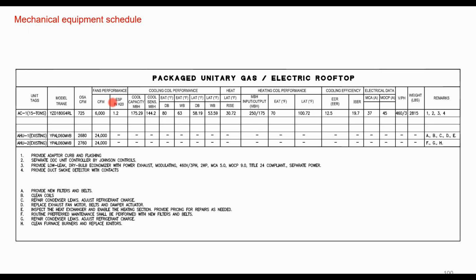There's a question there about exhaust fan energy being considered unregulated. Exhaust fan is not considered unregulated. If you look at Appendix G, the way that it accounts for fan energy, it's total system fan energy, right? So you have to account for supply, return, exhaust in your total calculation. So it is not considered process. If you had a kitchen that is doing exhaust, that is a process exhaust system, so that would be modeled neutrally. But in this case, this is part of this package system, so you need to account for it in the total system fan power.